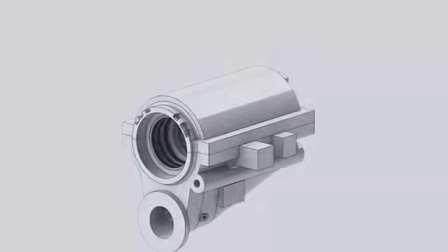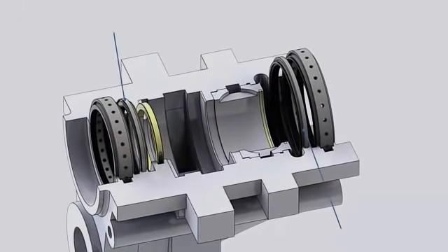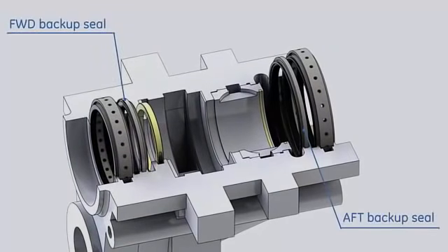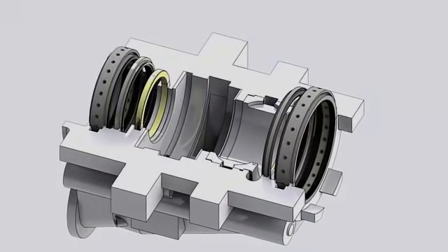Some of this air returns with the lube oil and is vented through the lube oil mist eliminator, and some escapes out of the housing. Inboard of the main pressurized seals, 2 backup labyrinth seals are installed for positive sealing. A floating seal is installed on the forward of the thrust bearing cavity to contain the oil.